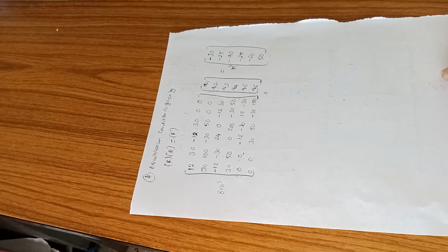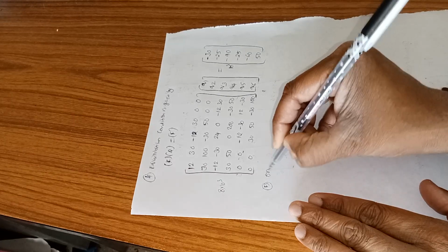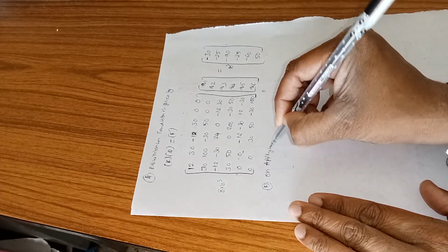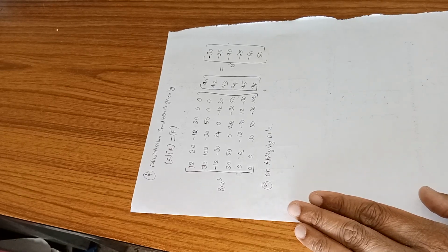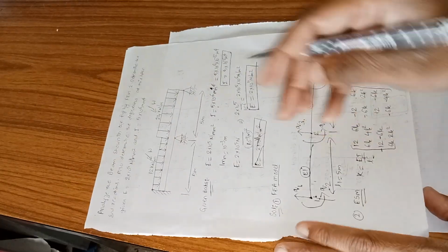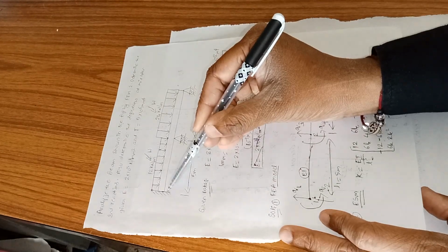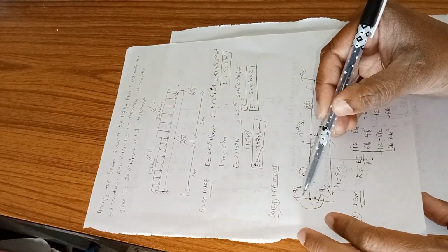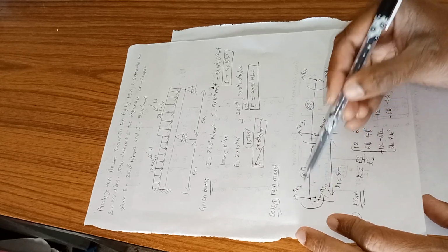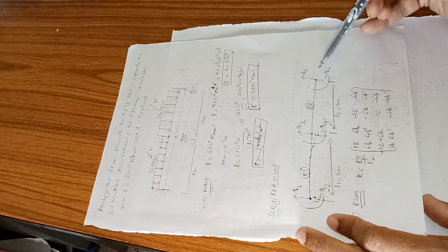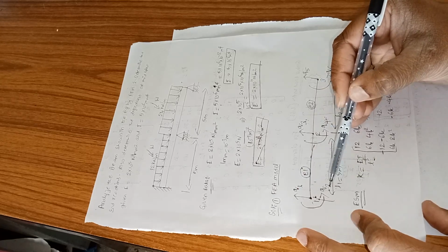So now I have to apply the boundary conditions. On applying boundary conditions, I'll take it as step number 5. BCs are nothing but boundary conditions. Here in this problem, let me mention clearly: this is node 1, this is node 2, the midspan, and node 3. At node 1 it's completely fixed. Therefore I'm going to eliminate node 1. At node 1 you have 1 and 2, at node 2 you have 3 and 4, at node 3 you have 5 and 6. As node 1 is completely fixed, I'm going to eliminate the first row and first column, second row and second column.